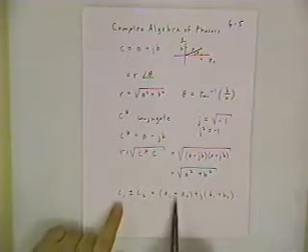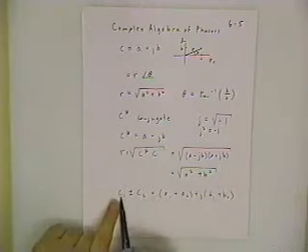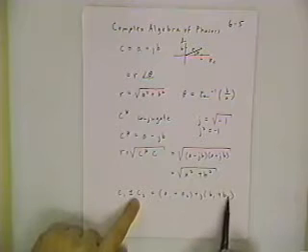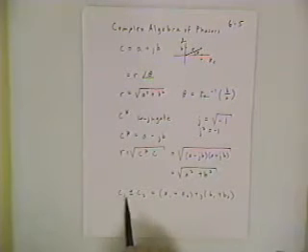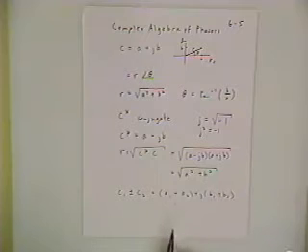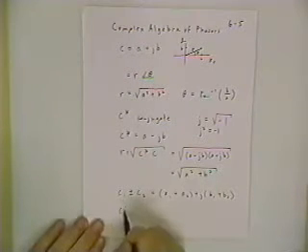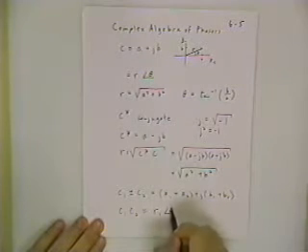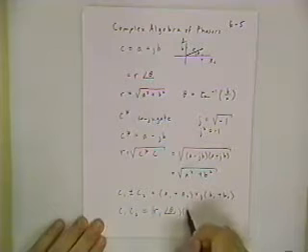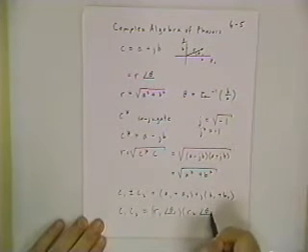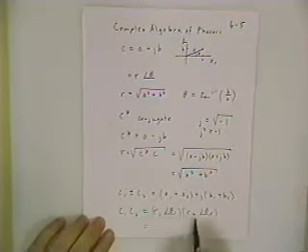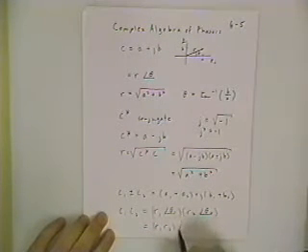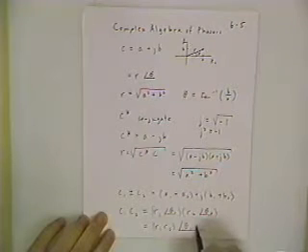Here the real and imaginary parts A1 and B1 correspond to the complex number C1. C2 in turn is equal to A2 plus jB2. And all I did to combine these was to combine real parts and combine imaginary parts. If you want to multiply them, the best idea is to convert over to the polar form first, and then multiply according to the rule that says the amplitude is just the product of the amplitudes. The phase angle is just the sum of the phase angles.